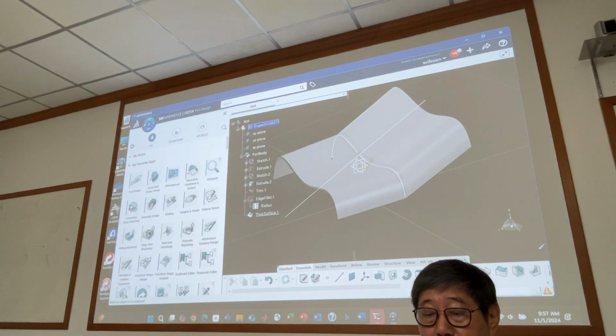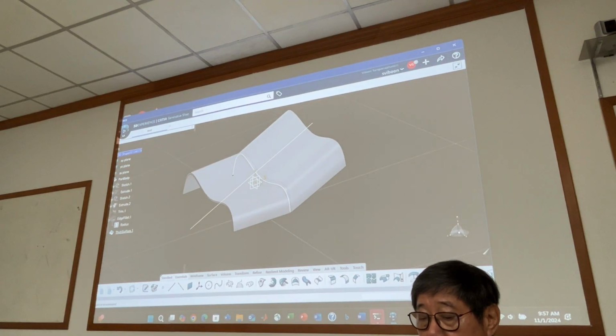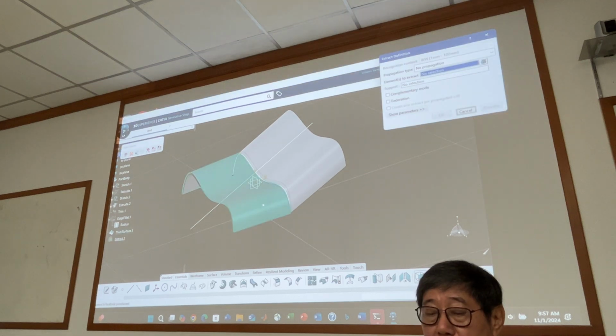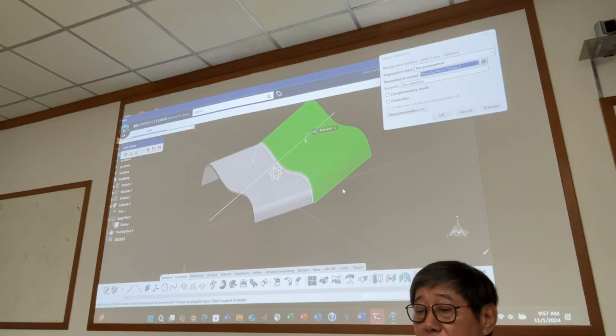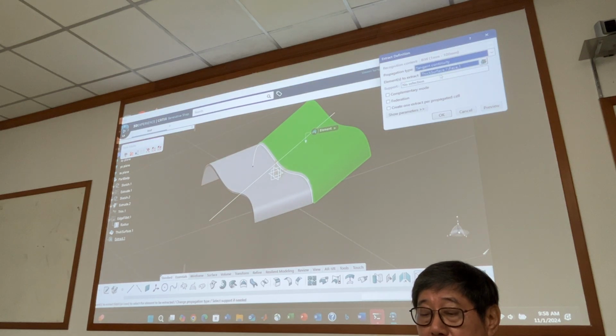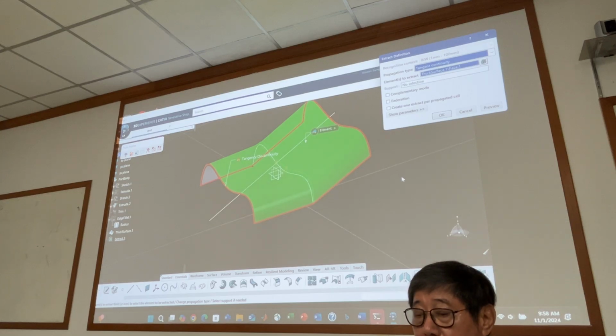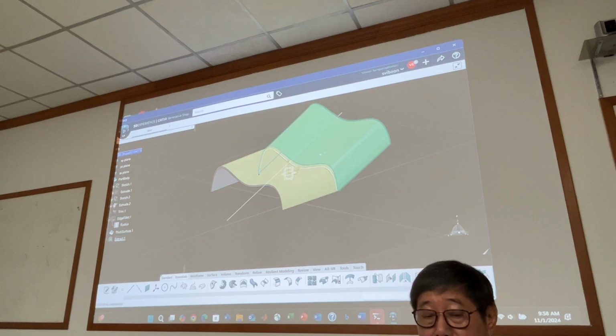If you go back to generative shape design, and you did it before using CAM model, right? Extract. This one, you can extract. I will use tangential property, tangential quantity. See this one. Okay, now you have surface here. This surface and the previous surface are not the same.